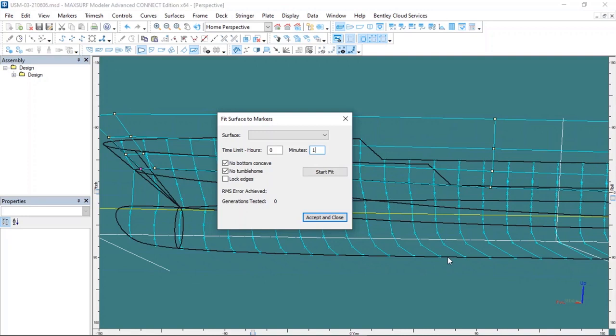If you don't want such an optimization process regarding concavity or convexity to be attempted in iterations, you should leave the boxes here marked. The log edges option at the bottom logs the edges. So, if you are satisfied with the location of the edges, you should mark this box. When you mark it, the location of the edges doesn't change.